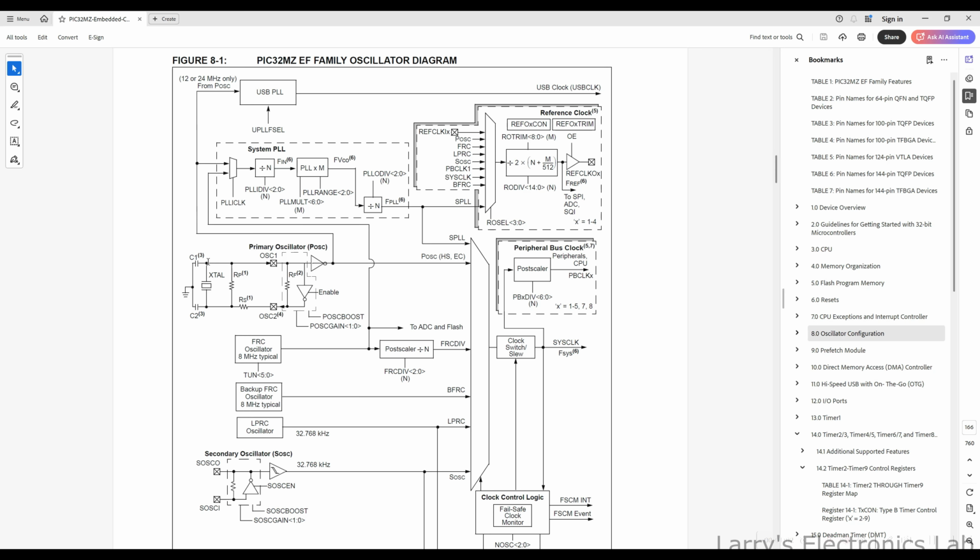With an oscillator, you just use the one pin for the clock coming in, and then this other pin, in some circumstances, you can use as an output, a divide by 2 of the clock coming out, but not in all modes.